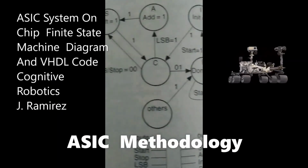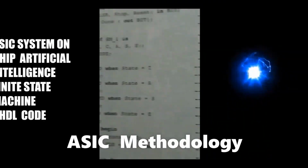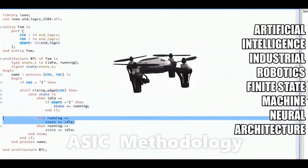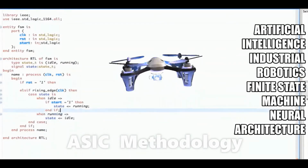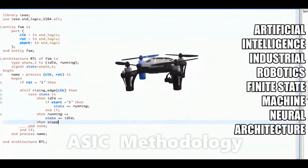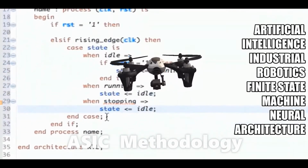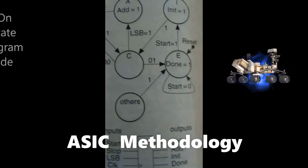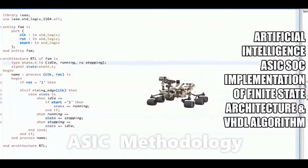The finite state machine, FSM, is a mathematical model whose output is dependent not only on the current state of the input, but also on past input and output values. The state machines generated in VHDL, as I have presented in this video, are clocked processes whose outputs are controlled by the value of a state signal. The state signal serves as an internal memory of what happened in the previous iteration.